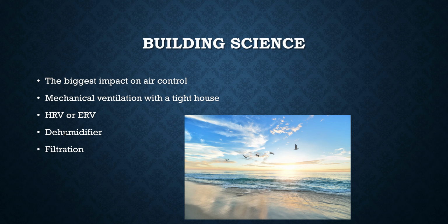So that's pretty cool. Of course, you can have dehumidifiers built into a central system. And the basic premise there is when you have a dehumidifier, you have exact control over the humidity and the amount of moisture content in the air in your house. When you don't have a dehumidifier, you are relying on your evaporator coils to dehumidify your air. Remember in that drawing, I showed you that when the cool house air is running past the coils, it's condensing on those coils and removing moisture out of the air. That's dehumidifying the house.